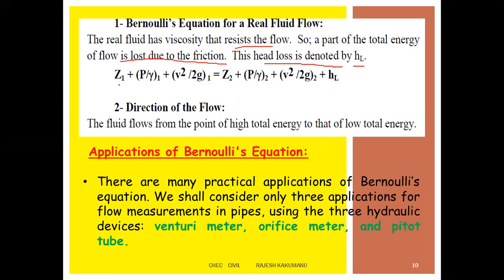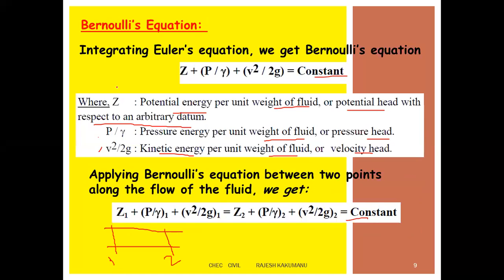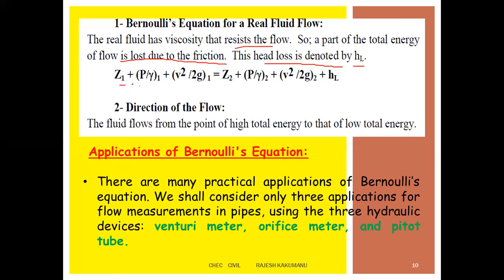Therefore, pressure energy plus kinetic energy plus potential energy (datum head) is equal to pressure energy plus kinetic energy plus datum head plus head loss, right? So this is the formula for the real fluid flow, the Bernoulli's equation for a real fluid flow.